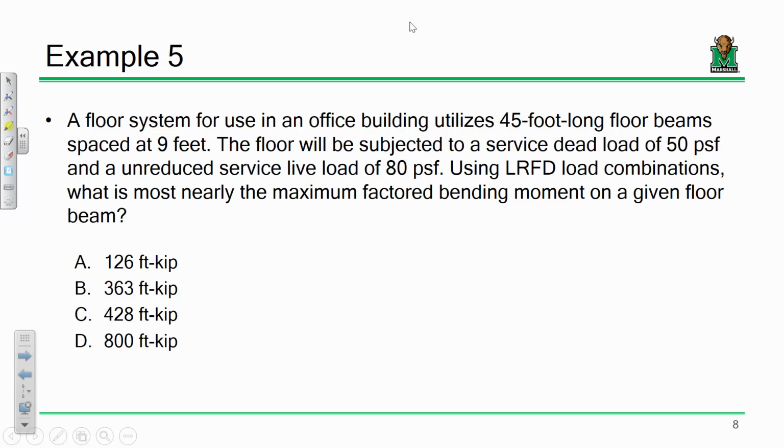Because we're dealing with simply supported beams and uniformly distributed loads, we can use a maximum moment of WL squared over 8. I think that's pretty straightforward. Let's chug this one out. I think you're going to find this is pretty simple.